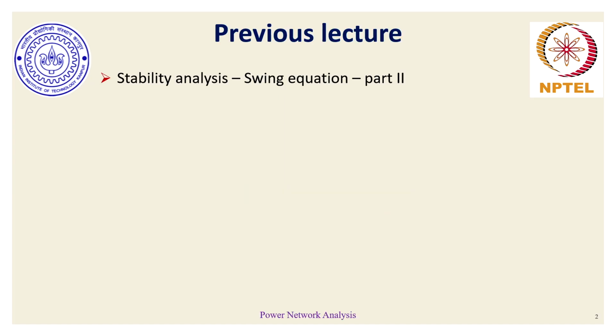In the last lecture, we had discussed at length various aspects of the swing equation, how swing equations exist for every synchronous machine in the power network, how with more renewable integration the H value is likely to go down and the chances of instability tend to go up. Details will obviously be discussed at length in the last lecture of this entire course or module. We also understood different aspects of reducing the number of swing equations based on coherency or non-coherency between the different synchronous machines. So why do we need Ward reduction? Let's understand that a bit.